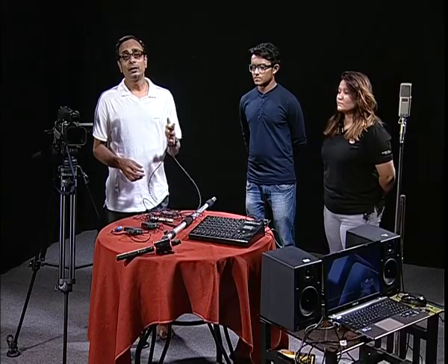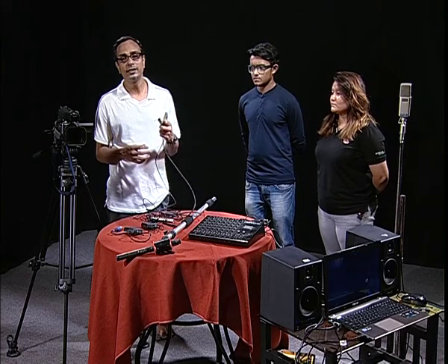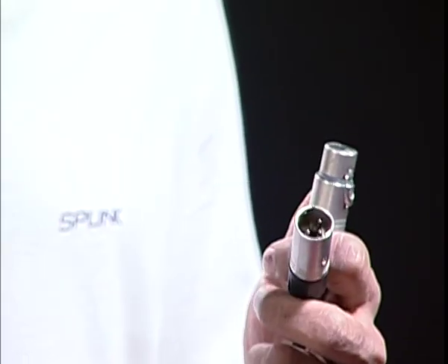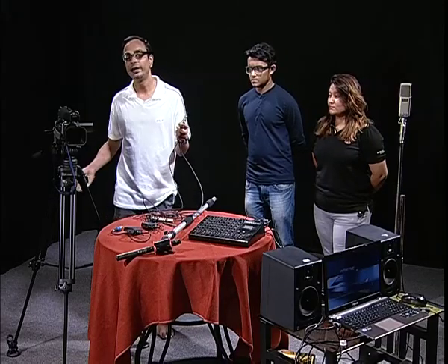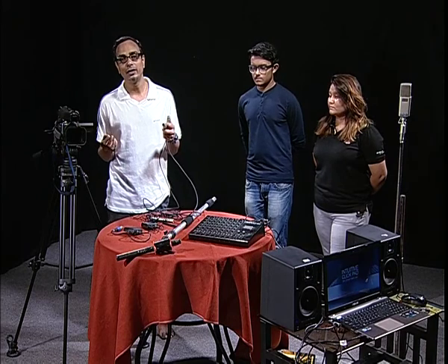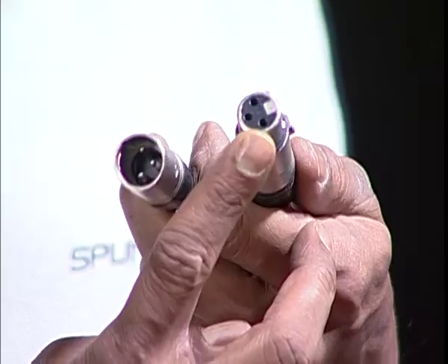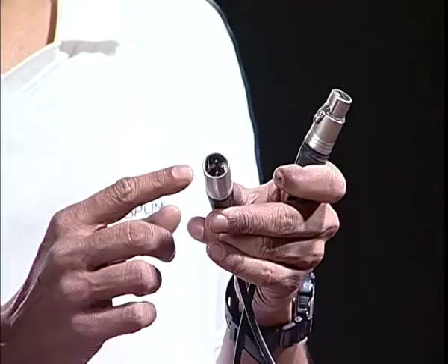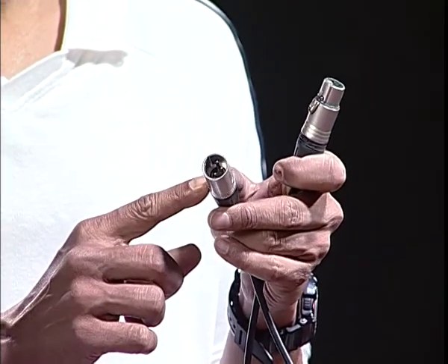The cables are also a very important linking factor between all the devices that we are going to use during recording. Now during recording, we'll have to lay long cables. Therefore, they are prone to catch several noises, and that is why we use something called a balanced connection. Here in this cable you can see this is the female side of the cable and this is the male side, and this type of connector is called an XLR connector.